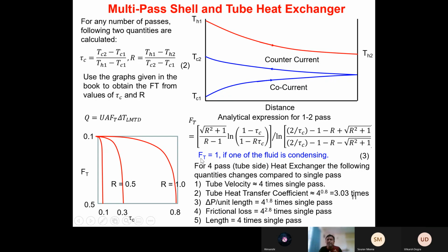Remember in the heat exchanger, one fluid is releasing the energy, whereas the other fluid is gaining the energy. But very often we use condensing steam, that means we are using saturated steam. So that fluid is not changing its temperature along the length of the heat exchanger, isn't it? Do you agree with me or not?